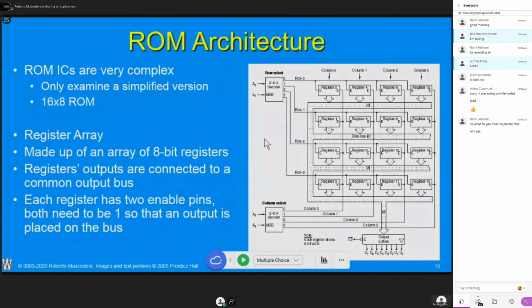Okay, so using 2 decoders makes more sense because, when we build our semiconductors, they are on a flat plane. We can't build transistors on top of each other. So we need a way to say, how do I turn on which transistor, so to speak, in this plane? It works well that way. Now it's possible to add more decoders, but you have to ask what that is going to control. In real world memory, another decoder might be used to activate a different bank of memory. So we might have an array of these 2x2 chunks of memory, and we just say, which one of these arrays do we turn on? It makes it a little bit easier to manage.